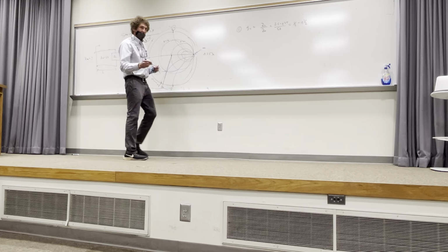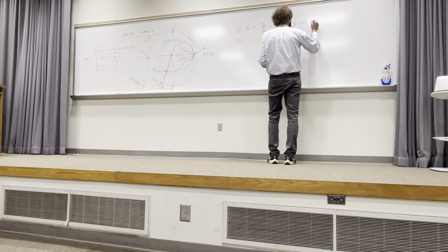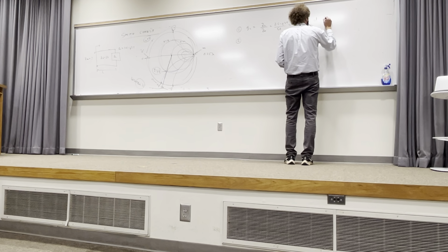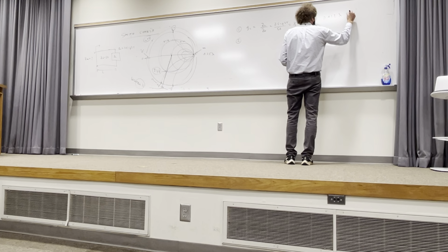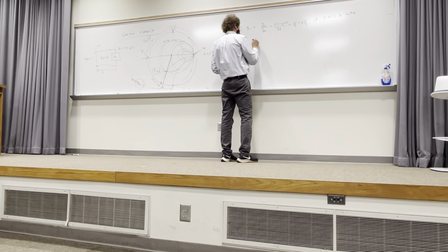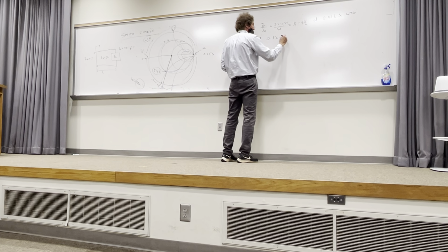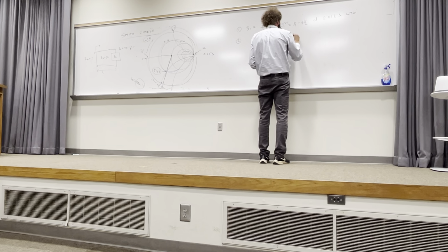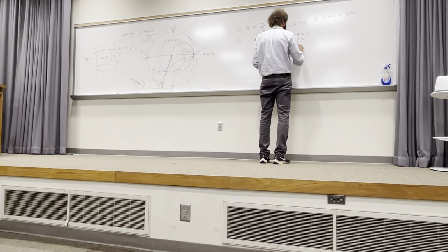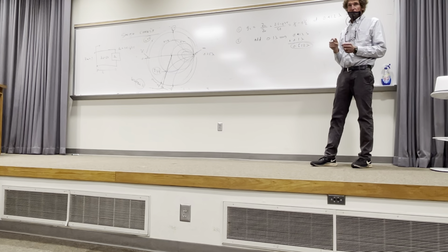So when I take a look at this, I notice that we're at 0.412 lambda wavelengths towards generator. I believe that was the location. Now we're going to add 0.1 wavelengths to it. So that means I'm going to have 0.412 lambda plus 0.1 lambda. That's 0.512 lambda. You all follow me?